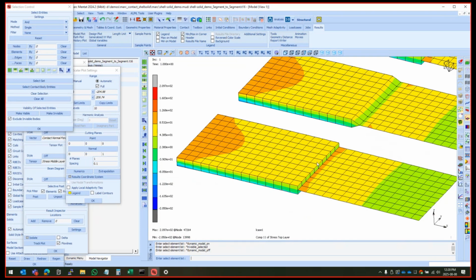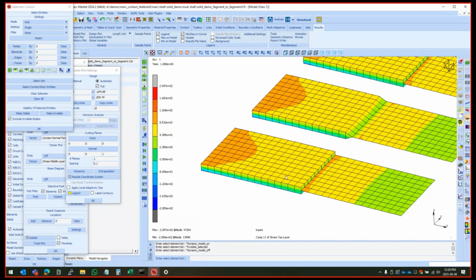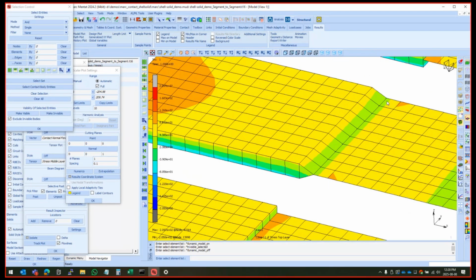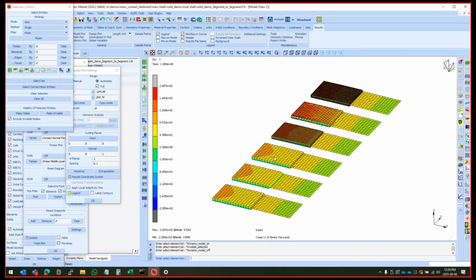both of these are relatively limited because we can only have one through the thickness. In theory, I can have two through the thickness there and still make it work, but more than that, it won't work to connect from the solid to the shell using rigid connections. In this case, that only allows, and again, we may be able to tweak it a little bit, but ideally probably one through the thickness. If I look at my stress patterns, these are not quite converged yet.